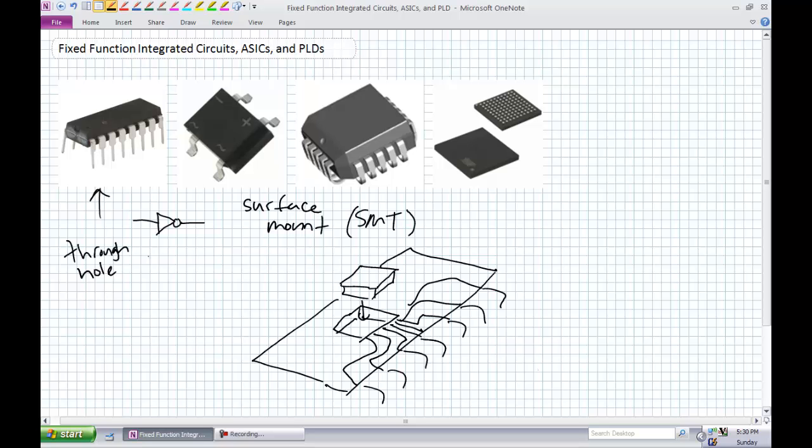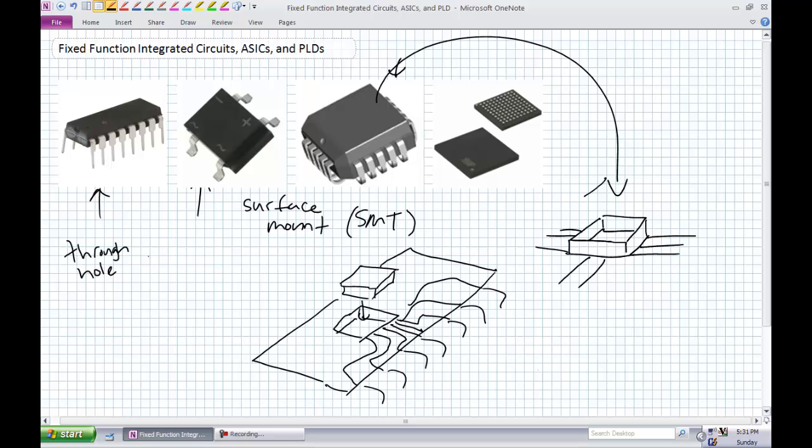Okay, the surface mount technology saves a manufacturing step. You don't have to drill a hole through it. Okay, you still have leads that need to be soldered, and in the one on the left hand, this one right here, you still need to solder those little wings to a copper lead. This one right here fits into a special socket, which is pretty cool. If you can imagine this little socket sitting on top of a printed circuit board, and all the connections to the outside world it needs is there, and that guy just kind of pops into the socket, and all its interfaces are on the side of the chip and the side of the socket. So that's pretty cool. You got to make sure the socket fits.